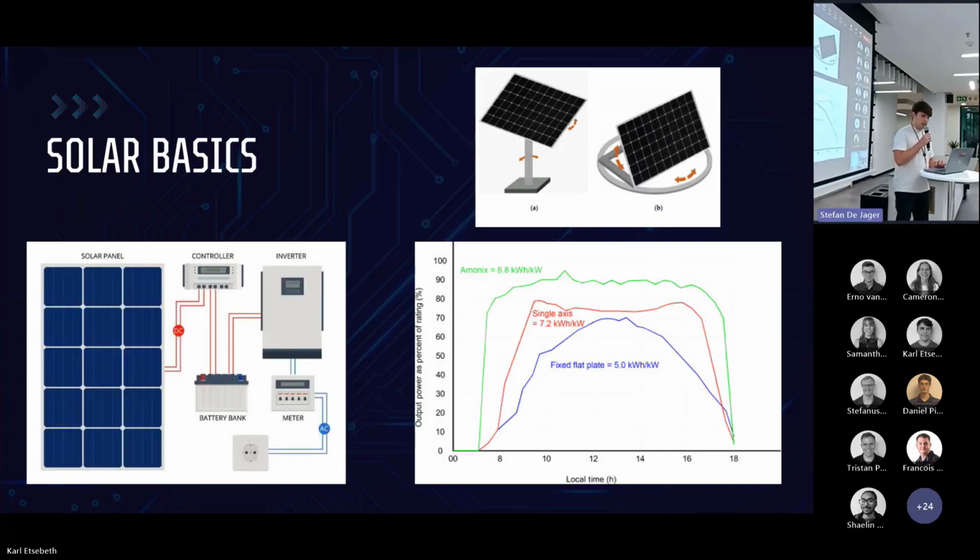An important technical aspect to note is that solar panels produce DC, while mains voltage, or what you use for almost anything, is AC. A solar panel's voltage output also fluctuates throughout the day. So an MPPT charge controller can be used to control the solar panel output to make sure it's more constant and can actually charge a 12-volt battery at typically 13.8 volts.